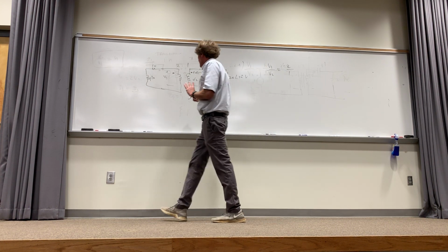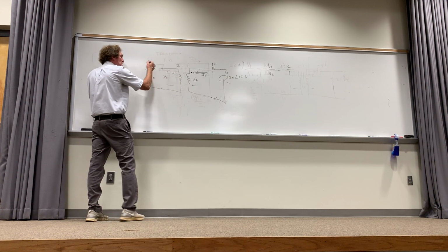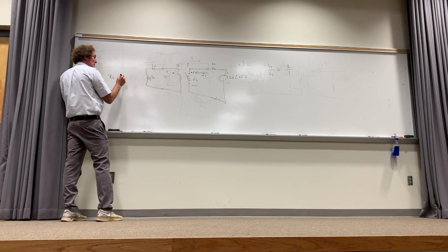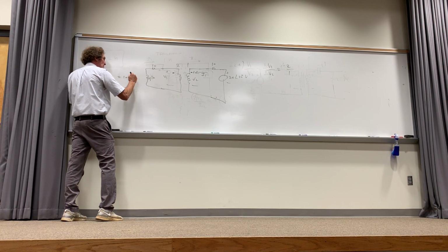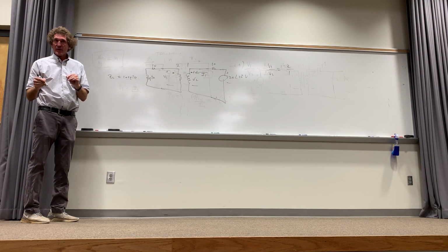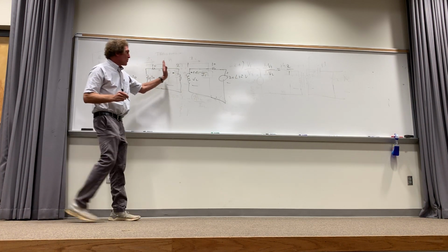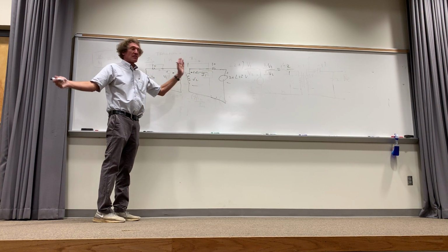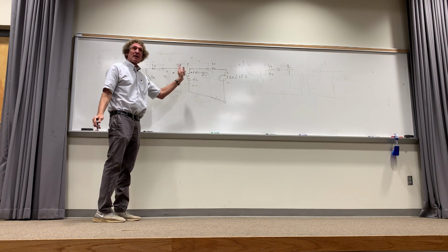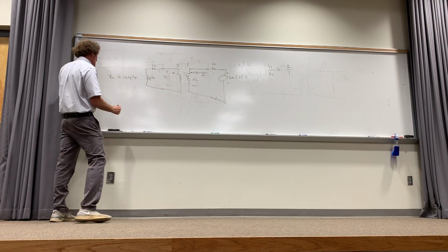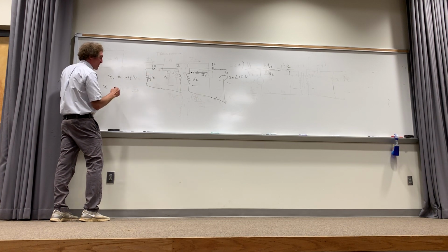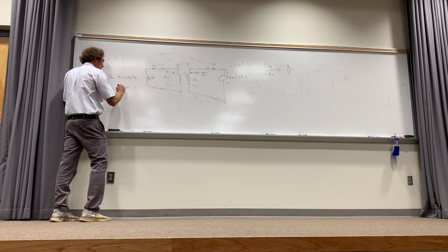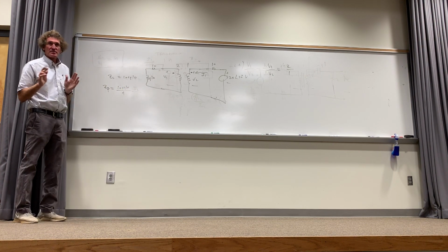What we're going to do for this one is first take a look at the impedance in the secondary circuit. So the load impedance in this case is on the primary, but it's the load. That's 10 plus J10, right? Correct, class? Then we go from more to less, which means the impedance goes down. It goes from more to less impedance by the square of the turns ratio, or by 4. So that means Z, on what I call the primary, it's really the secondary, but now on the reflected side, would be 10 plus J10 over 4. Do you all follow me on this?